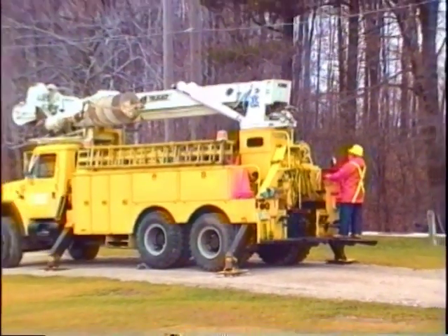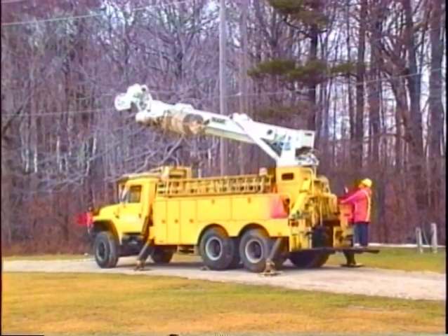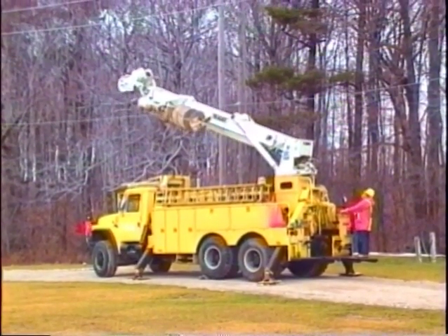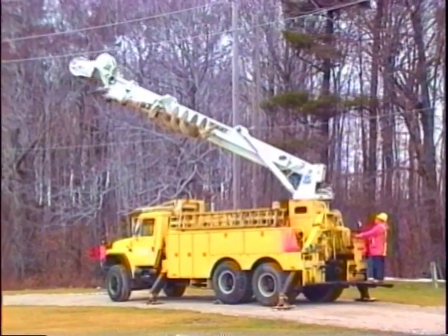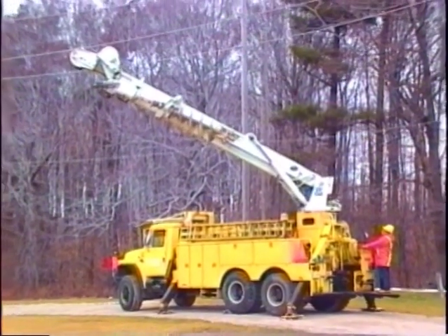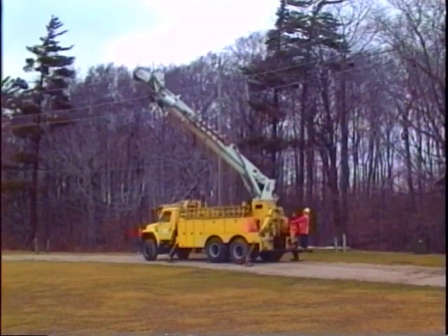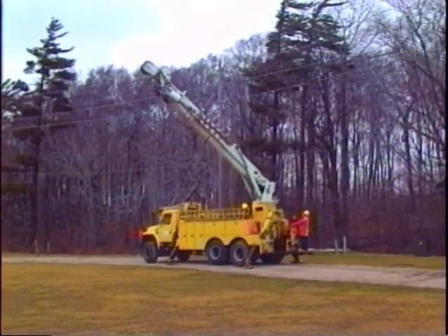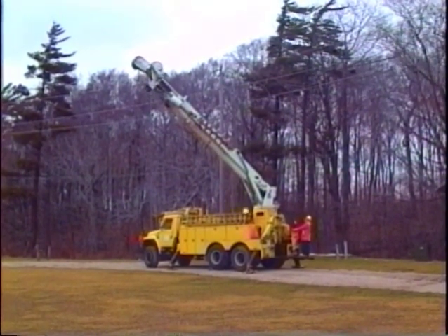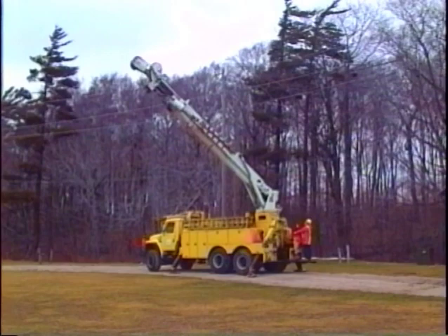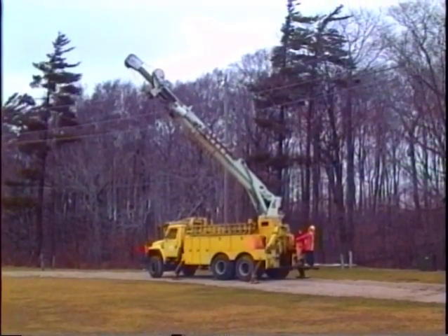On a digger derrick, the test sequence is the same, but the boom position is different. After checking the outriggers and purging the system, raise the boom to approximately 60 degrees. Extend the stingers or extension boom halfway out, and carry out the holding valve checks as before. If the holding valves fail the tests, re-purge the system and try again. If there is still a problem, send the vehicle in for servicing.